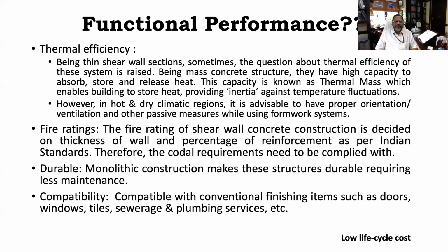Number one. Secondly, most of the heat comes from the slab. So if the slab, meaning roof or floor, is treated properly and given a proper thickness, half of the problem related to thermal comfort can be eradicated. So because of the mass concreting, one thing is thermal mass. Secondly, if you have a proper roofing system with sufficiently good treatment, thermal comfort is not a problem.